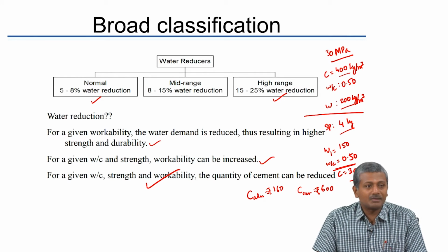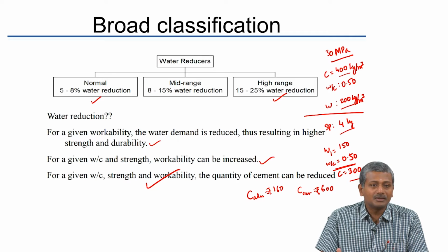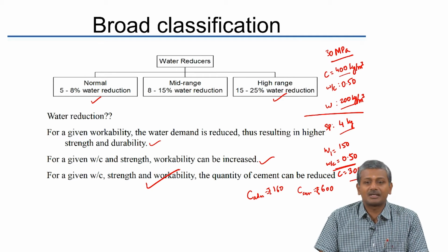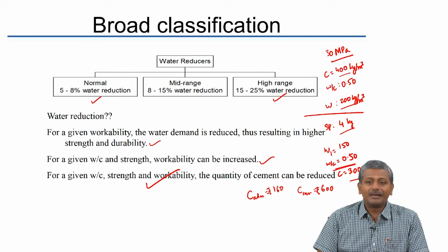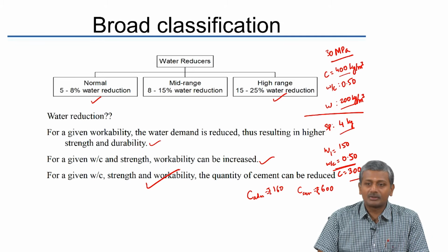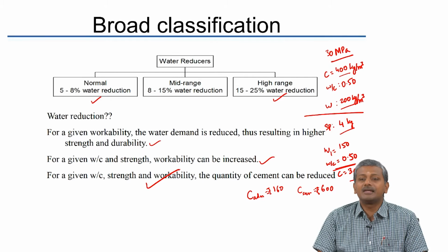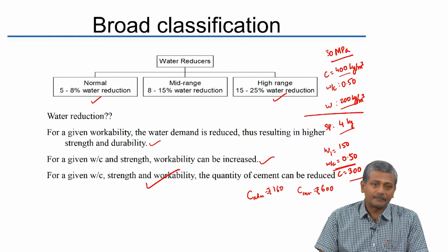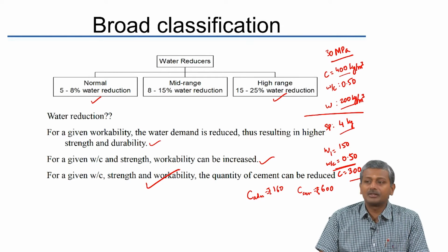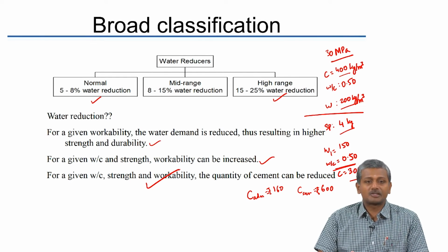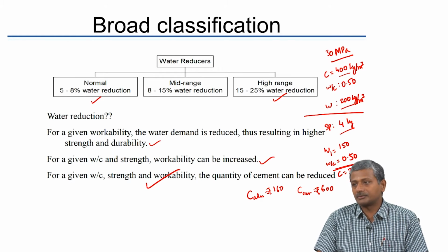And in fact, today, very interestingly, I have also seen that many people have the habit of still putting proportions together even after a weigh batching based mix design has been done. So, people find out the weights in kilogram per cubic meter and then represent the weights in terms of proportions of cement to fine to coarse aggregate. That is not the correct practice, because it can easily be misinterpreted as volume batching. So, you do not want to give that impression. So, as far as mix designs are concerned, we need to ensure that all our mix designs are specified in terms of kilogram per cubic meter of the ingredients and not in terms of proportions.